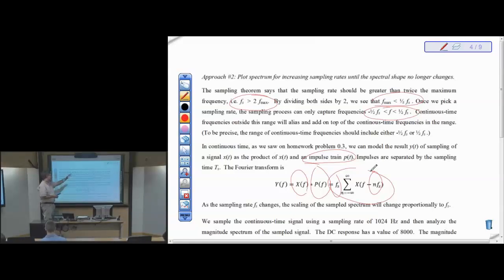Now in practice, whatever Fmax we pick, if it's finite, we have frequency content greater than that. So in practice, we'll always have aliasing. Bad news. There's at least thermal noise above whatever frequency. Anything at or above half the sampling rate, for the rates that we sample at, we're going to have thermal noise and other things. So in practice, we always have aliasing. If it bothers you a little bit, yeah, it bothers me too, because the theory says we somehow can get around this, but in practice, we can't.